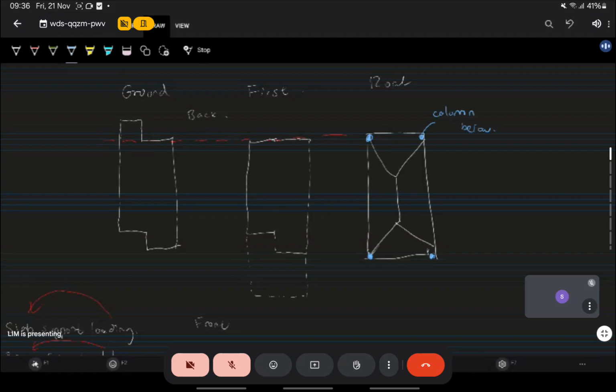When we show beams, it's the beam at that level. Now the next thing you have to do: we have columns, and the columns need to support the beam. So you can start putting beams between the columns. These are your beams. You take the architectural plan, take a marker, and mark where the column goes, where the beam goes.